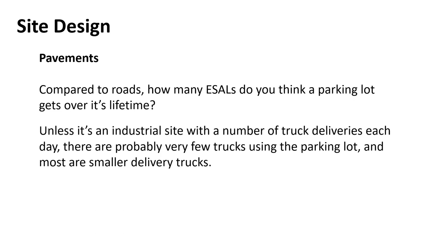Now, an industrial site, if you've got a Walmart and the loading path where trucks are coming in and out, yes, that will need to be a beefier pavement section. If your site development is for a concrete plant, okay, that's going to be one heck of a pavement there, right? Loaded concrete trucks coming in and out and aggregate hauling and all that going on. So it depends. Industrial sites, yes, they may have a significant number of truck traffic, but even then, quite often you separate the truck loading and unloading area and have its own access and its own turnaround area and all that. And there would be a separate parking lot for employees and so forth.